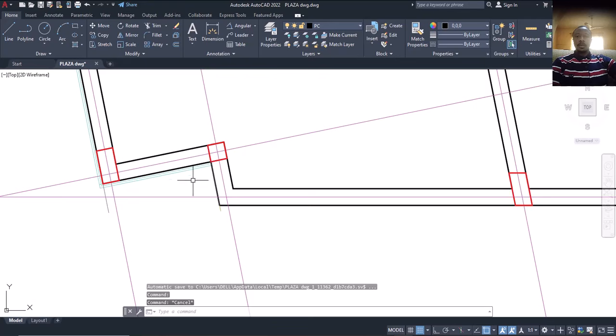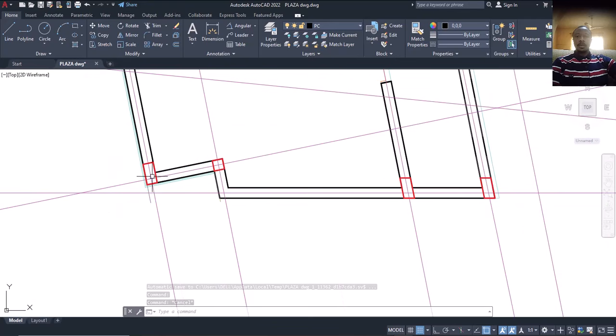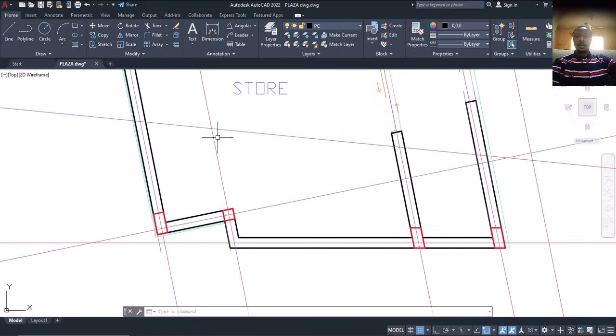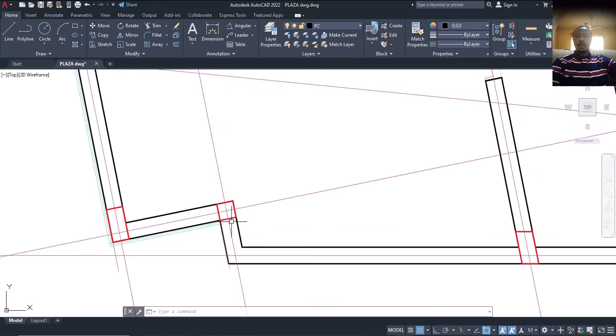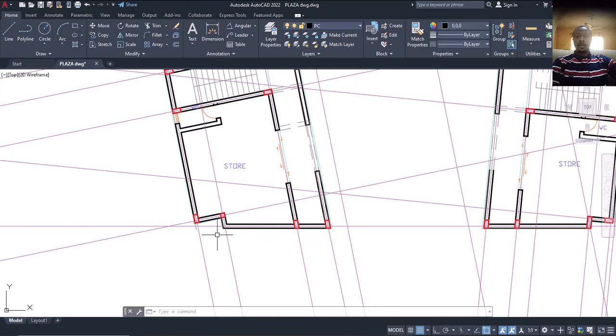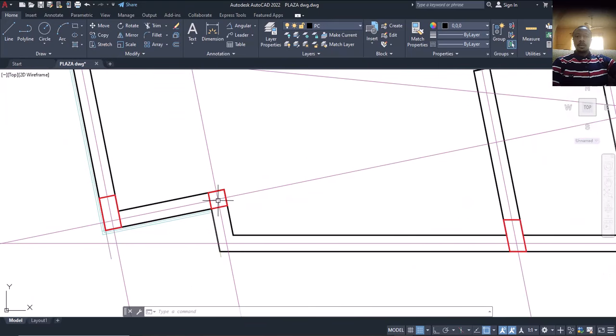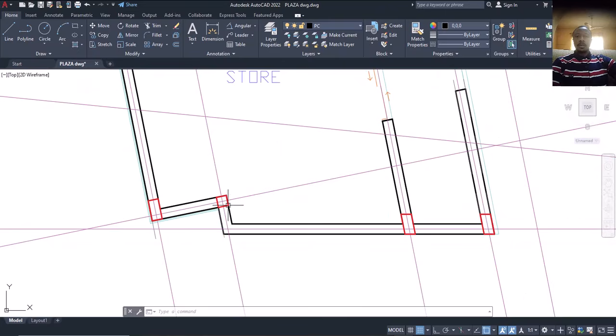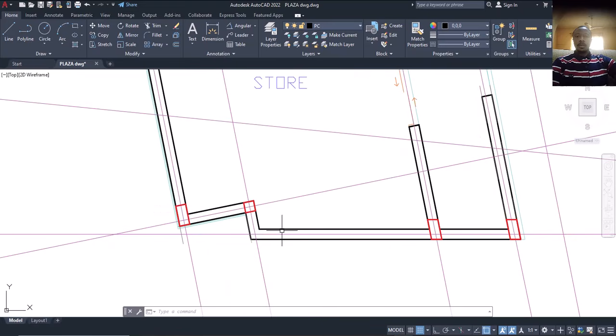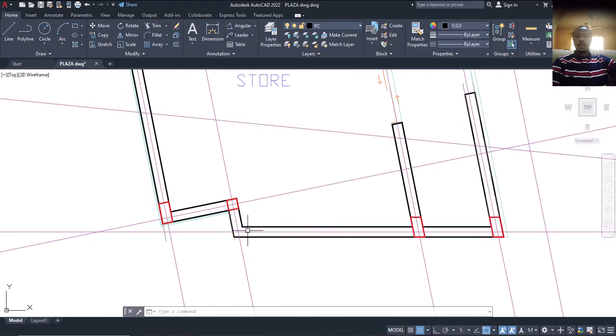Is that okay? Because just like what I explained that time, this place is perfectly stable, but here it's not stable. Because assuming I have a beam that is running from here like this, I can say yes, it's okay. This single column would have been okay. But since I don't have any drawback from here, the beam source is going to be from here, and it will be too small to carry this span. Is that okay? It will be difficult to carry this span. If not, it's going to be requesting a big depth, which I don't want. Is that okay? All right.